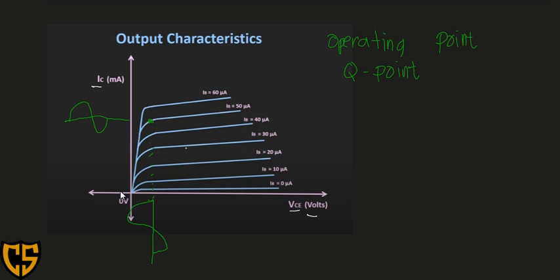Okay. So, there is a tendency that there will be clipped parts in our signal, because there is a part that goes beyond 0. Your VCE cannot go below 0, so there will be a clipped part. And what if your signal is in the upper part? You have your signal here, and in the upper area you will have your signal represented like this.